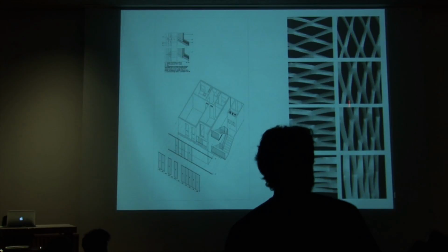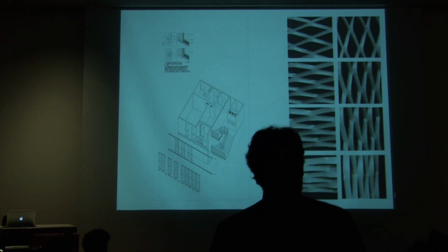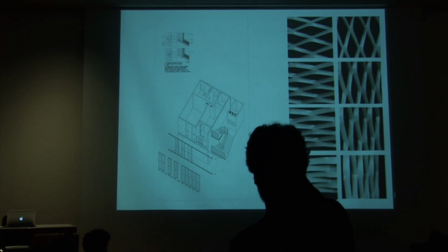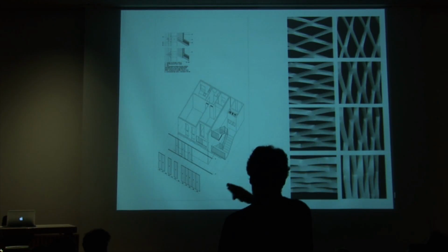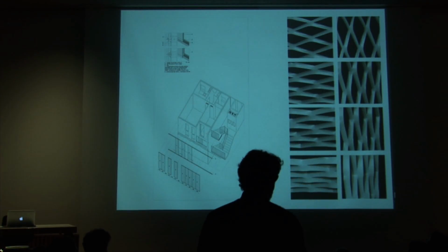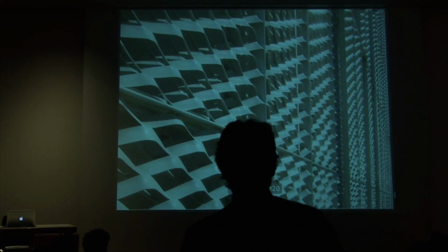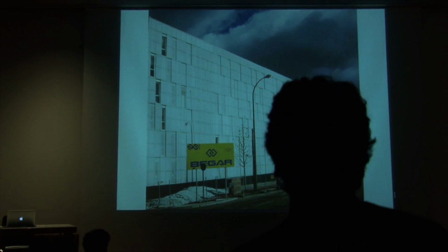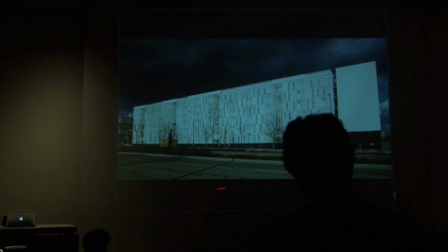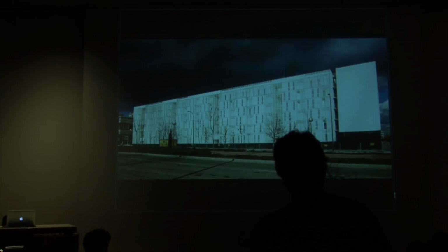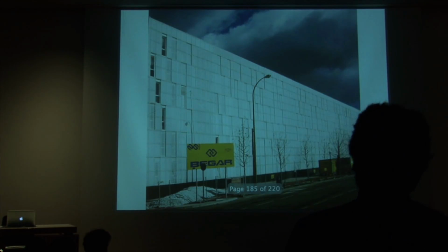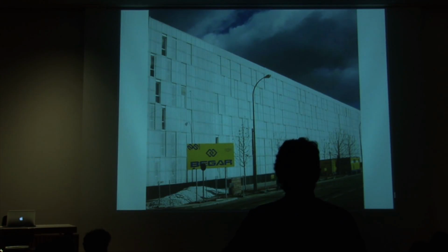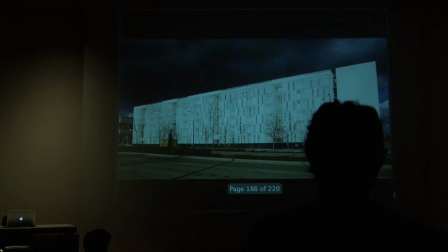And it's placed like this on the west facade because we profit from the different position of the sun in winter, right? Because in winter the sunset is more to the south, so it is southwest, but in summer it is more to the north. So the building that is completely opaque to the southwest, the same facade, if we have a look from the southeast, then it is more transparent if we place it vertical. So the sunset in winter would hit the building, but the sunset in summer would be more or less protected by this double facade that can be ventilated behind.